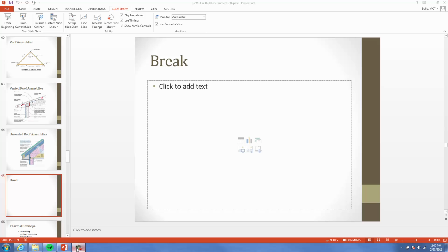What's that green sheeting they're using on the new Missoula College building, as far as what they're wrapping it in? That's an engineered product. That's actually part of the thermal envelope. It's a water resistant barrier with insulation in it. You're not going to see an OSB or any type of wood cladding on most commercial structures. They're going to use a steel frame and a wrap like that, just like a Dens Glass. It's a water resistant barrier, and it's the start of the thermal envelope.